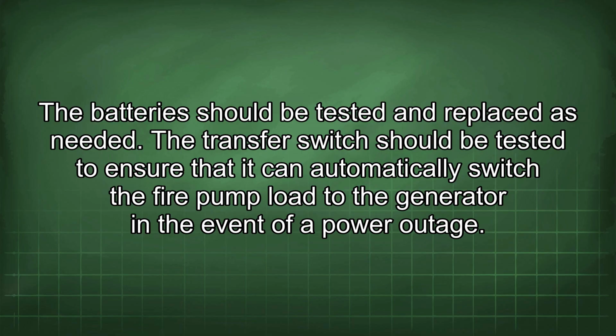The battery should be tested and replaced as needed. The transfer switch should be tested to ensure that it can automatically switch the fire pump load to the generator in the event of a power outage.